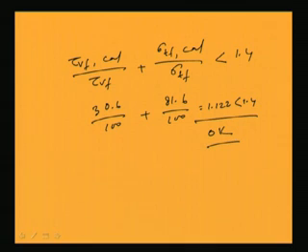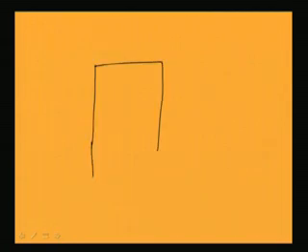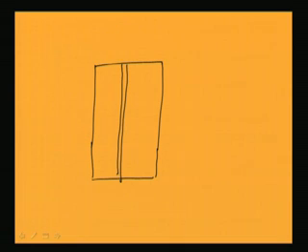Now, we have to make all the other specifications. That means we have to draw the connections. So how to do that? We know that the connection is a 2 angle ISA, and its width will be ISA 100 by 100 by 10. So this is 100 and this is also 100.